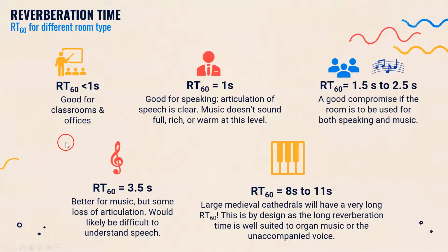Now, these are the reverberation times for different room types. Below 1 second is good for classrooms and offices. You already get the answer here. So it should be below 1 second. So how about others? Okay, 1 second is good for speaking, but not so good for music. You will hear the music as if it's a little bit dull. So RT equal to 1.5 second to 2.5 second is a good compromise if the room is to be used for both speaking and music.